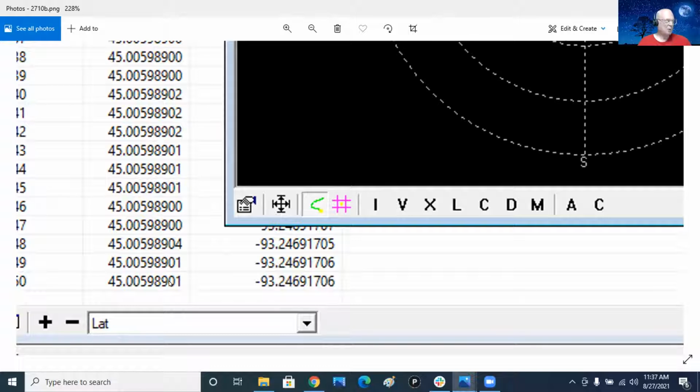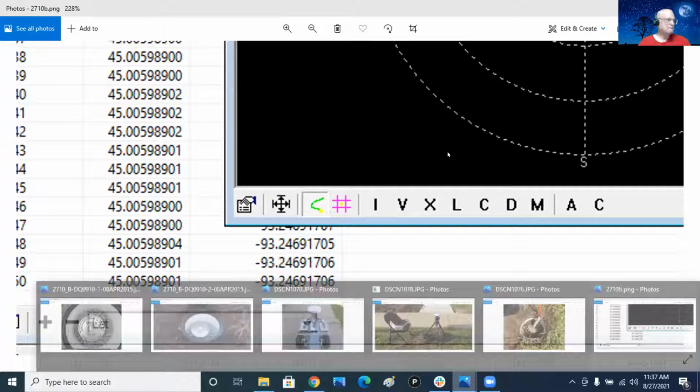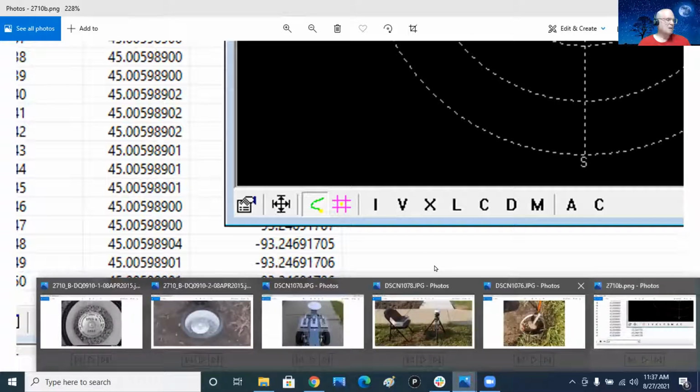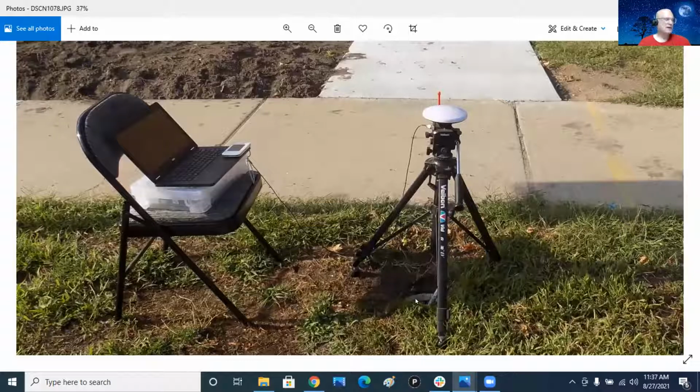And so I multiplied the 2.75 that I was getting by 1.1 meters, and it comes out to about 3 centimeters at that point. So I'm thinking that it's telling me that if I look at my setup here, it looks like I was like 3 centimeters further north than what it says it is. And the fact this is bent and I'm just trying to eyeball the alignment, and it's probably not level, you know, I'm just tickled with that. The fact that it says I'm within 3 centimeters of some other pre-surveyed location, that's great.